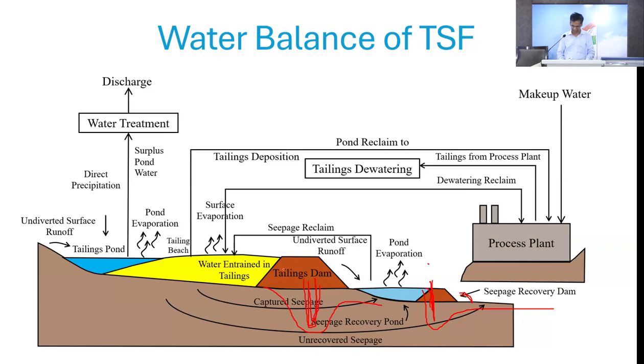So just to check whether that geomembrane is working or not, I told them to install 2 piezometers. Like here the water level inside is known to me. I am putting one here and the other here, away from it.